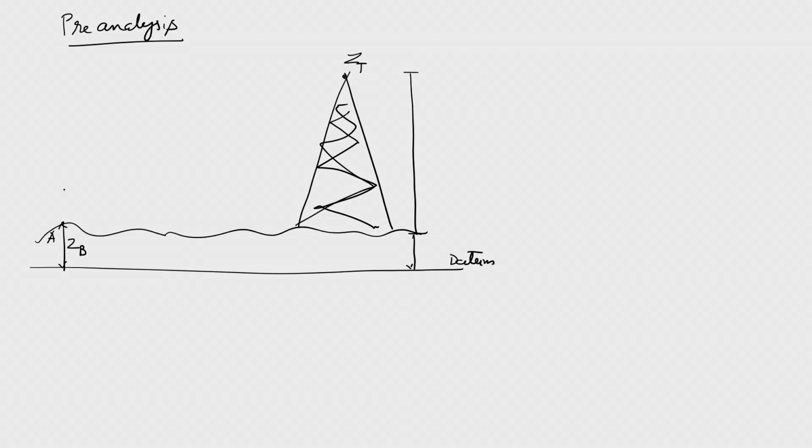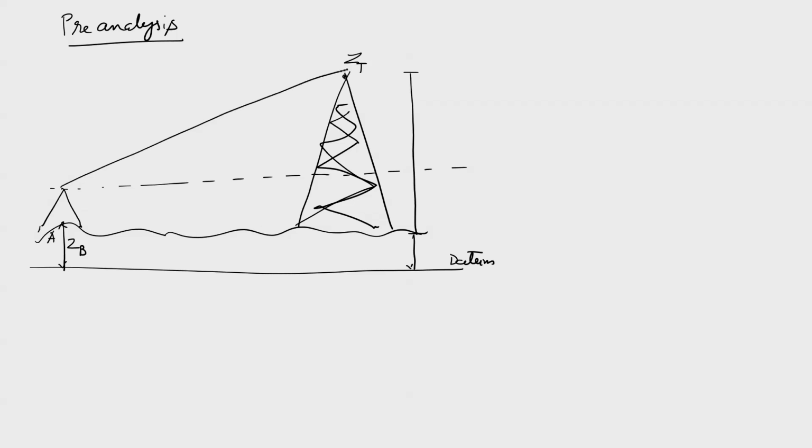Now, you put a total station over there, at this point A, and then you establish a horizontal line of sight. Then you measure this distance, let us say D, and you measure the elevation angle alpha, and the distance, that we do with the help of the total station. Now, if you also measure the height of the instrument, capital H here. So, let me write ZT is equal to ZB plus H plus D sin alpha. That is the ZT, you can determine it by putting these values, but what is the sigma square ZT?